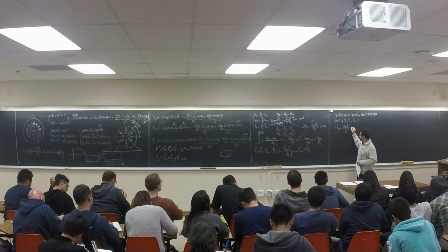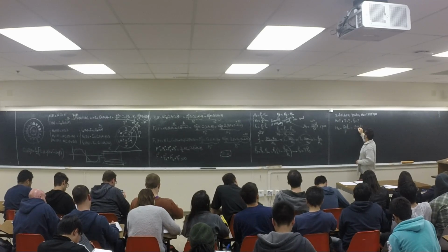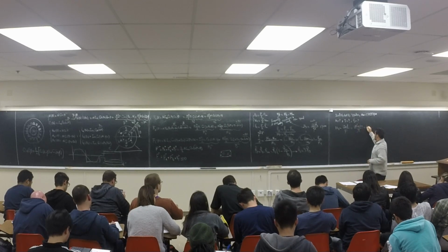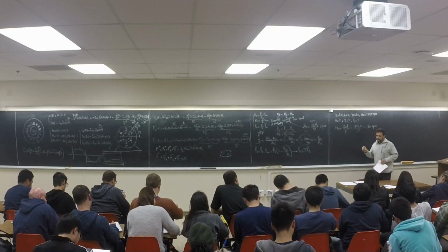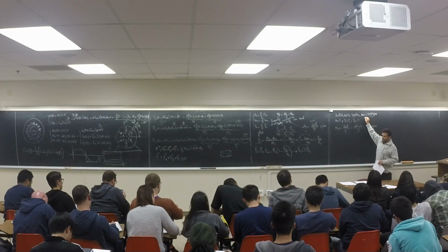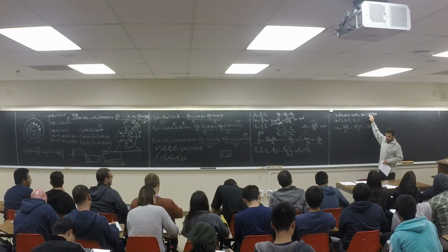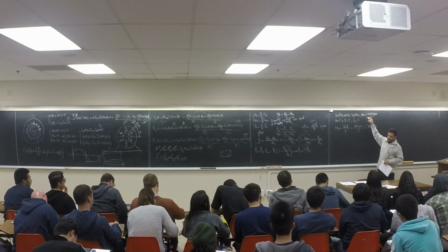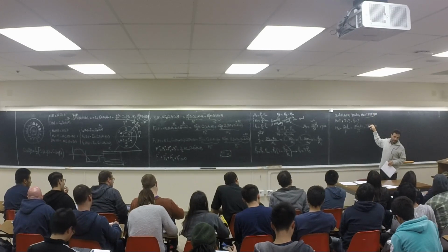So it's going to be 120 times 60 over 4. So this is 30 times 60, which is 1800 RPM. Look here: this is the nominal speed, and this is the synchronous speed. Another thing to keep in mind: usually the speed of the rotor in the induction machine is very close to the synchronous speed.